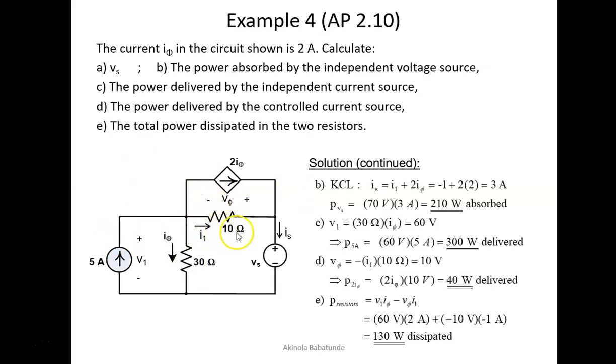What is our R here? It is 10 ohms. What is our I? Our I here is equal to, you will notice that the current is moving in this direction, and so the polarity or the sign of this current is going to be negative, because if we draw our closed path direction, which is clockwise, it is going to be going against the direction of this current.